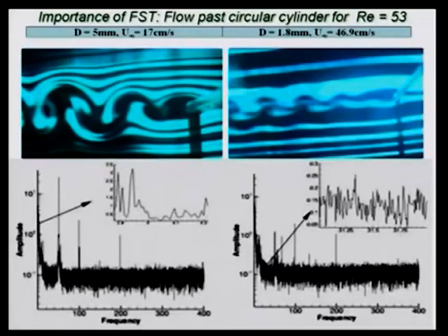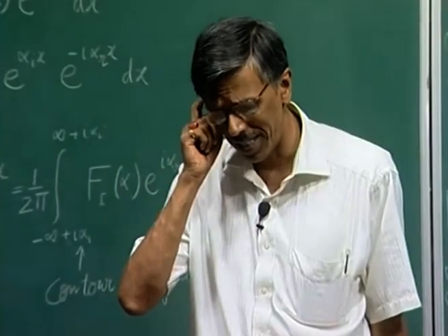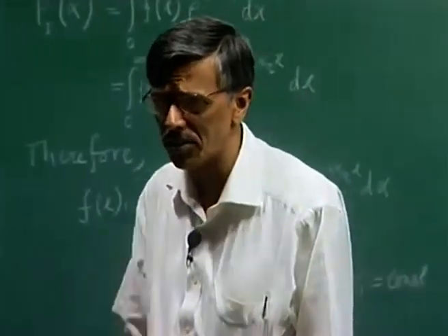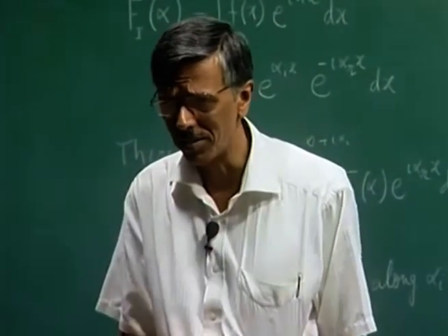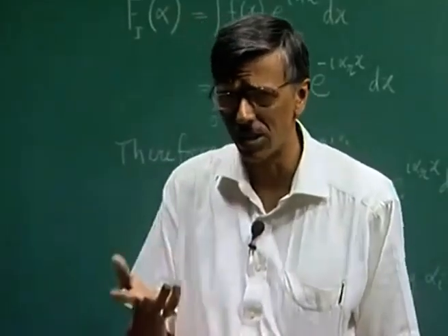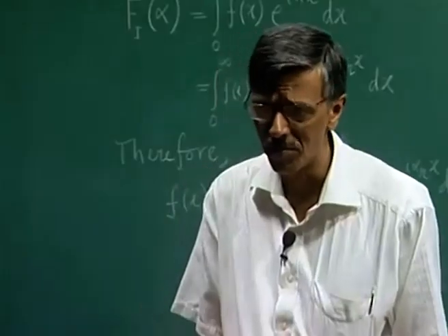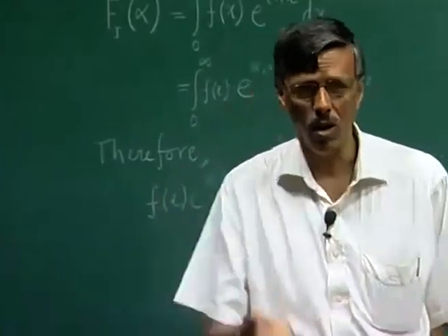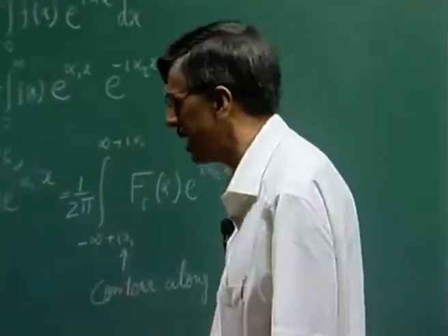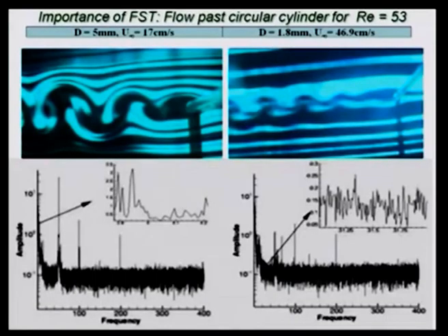And now, we did talk about free stream turbulence, right. How important it is, because the vibrating ribbon experiment of Schubauer-Skramstad showed that you could excite the TS wave by vibrating a ribbon inside the shear layer. But suppose the disturbance is outside the shear layer, that is what your free stream turbulence is most of the time, whether you are flying an aircraft or you are doing an experiment in the tunnel. It is what you are getting in terms of the background disturbances.